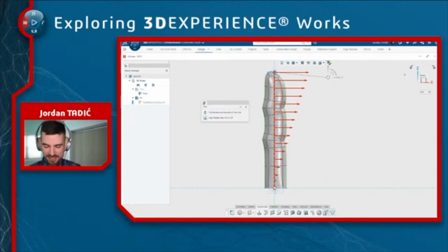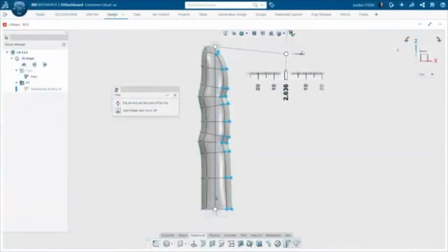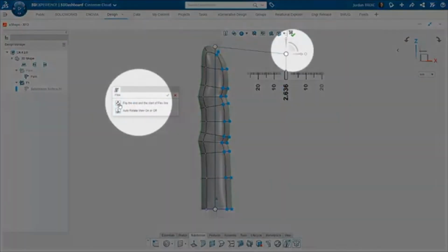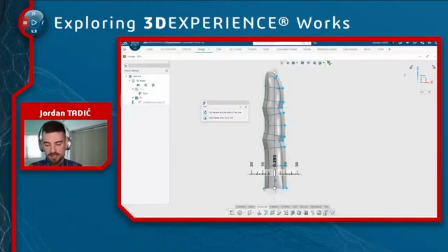Enough explaining. Let's just see this in action so you can see what I'm exactly talking about. I'm going to select all the entities on the side of this finger, and I'm going to drag the robot, and you can see how it influences up at the top more than the bottom. The bottom kind of stays static, and now we could add that tapered effect. So if I were to name this tool, as much as I like the flex name, I would call it the taper tool, because that's really what we're doing in most cases. Now, what if I wanted to drag the bottom outwards while keeping the top at the width that it was? I could just flip the side that the robot is attached to while maintaining that selection and drag outwards to taper the bottom outwards. So you could do this for the opposite side, the same effect.